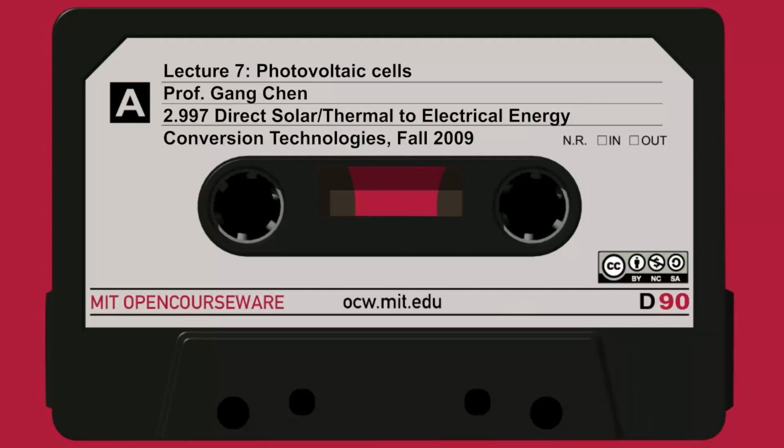Again, this is just mathematical detail, not important. But very often in the terminology, people ask, "What's your fill factor?" What is that? This is the rectangle where you optimize. You run at your optimum current-voltage point, right? So that's the actual maximum power you have.